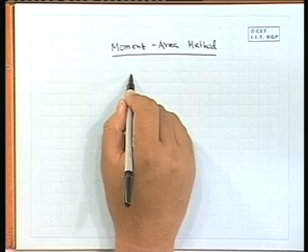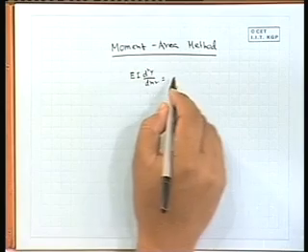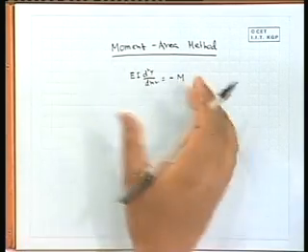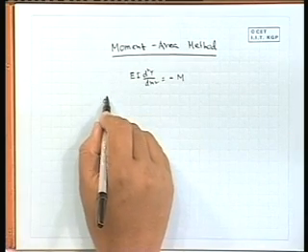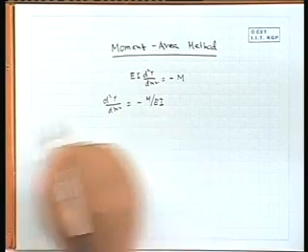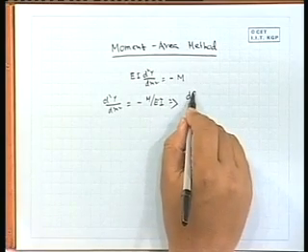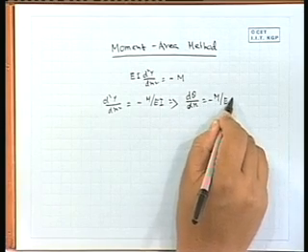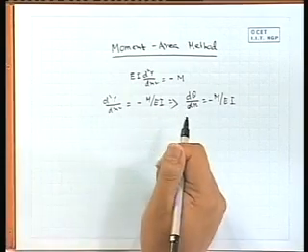We have the understanding that EI d2y dx square equal to your minus or plus whatever M is there. So, this we can write as d2y dx square equal to M by EI, or that equation we can write in this form, d theta by dx equal to minus M by EI, because theta is basically dy by dx.